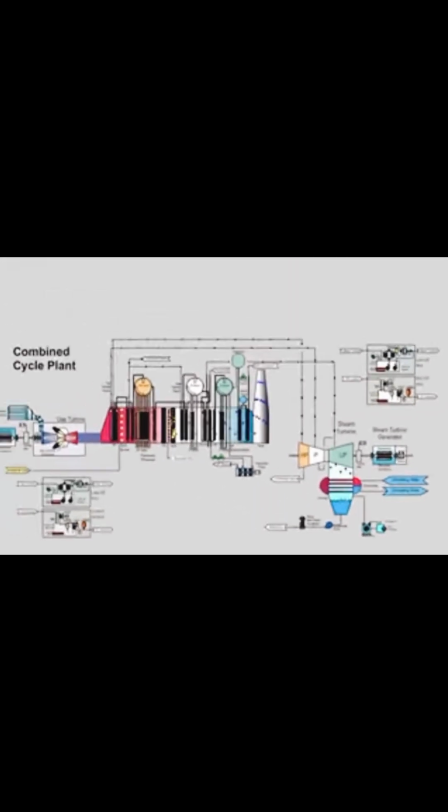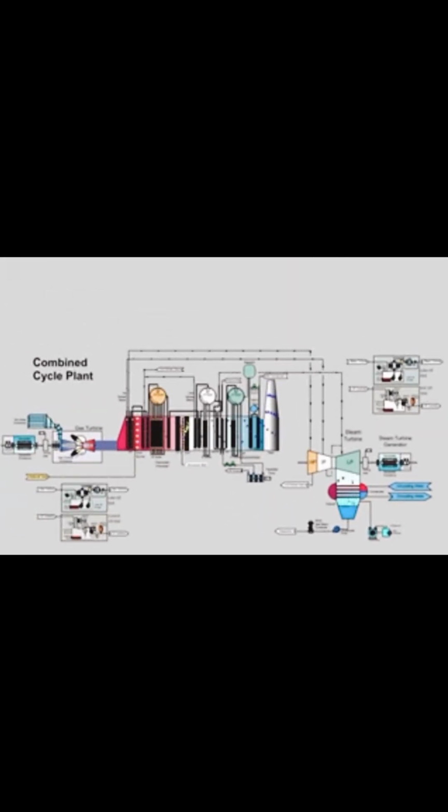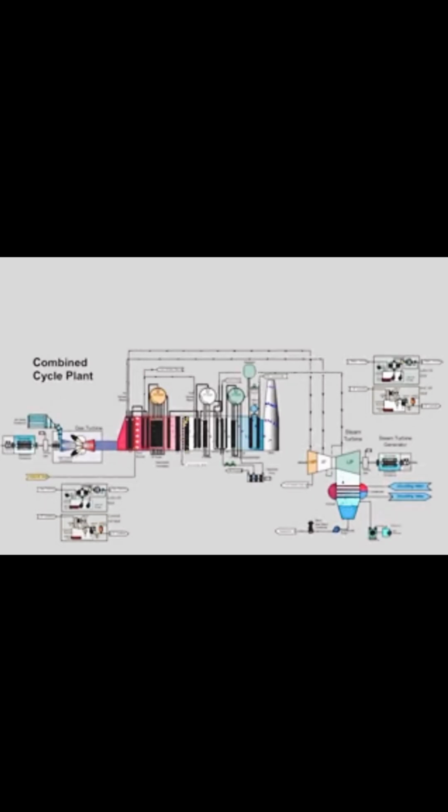Each turbine and associated generator has necessary support systems to facilitate their operation. Some of these include lube oil systems to provide cooling and lubrication, control oil systems to provide hydraulic operation of control equipment, a turning gear, and other necessary systems depending on the particular design utilized.